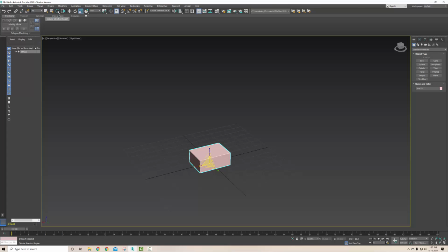The same thing applies to the select tool. If I click and hold on the select tool, you can see all my different select methods. By default it's square, but every time you hit the Q key, you can see it switches. So you have to be careful with that. It can actually get confusing, like you can hit it accidentally and now everything you're selecting is a circle. You have to be aware of what you're doing, or you click it and now you're selecting everything in a polygon. You can click and hold and just reset that. So that's your basic movement and basic scaling and rotation stuff.